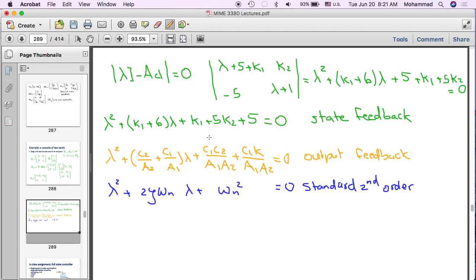where K affects. What coefficient in the characteristic equation is going to be affected by changing K? Is the coefficient of power 1 of lambda being affected by changing K? Do you see K at all here? So that means K is not affecting the combination of zeta and omega n. But when you look here, you see K, which means K is going to affect omega n.